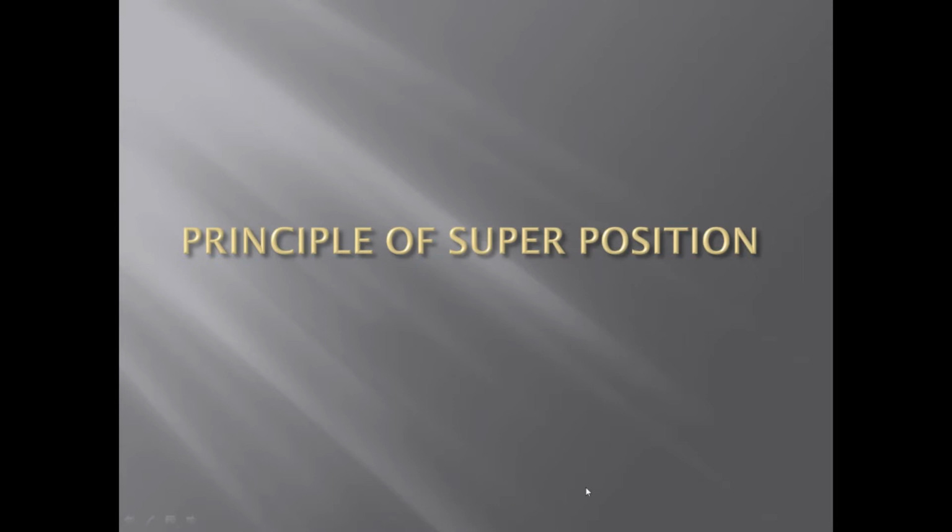Principle of superposition. Sometimes a body is subjected to external axial forces, not only at its ends but also at intermediate points of its interior cross section along the length of the body. In such cases, the forces are split up and their effects are considered on individual sections. The total deflection is equal to the algebraic sum of the deformation of the individual sections. This principle of finding the resultant deformation is known as the principle of superposition.